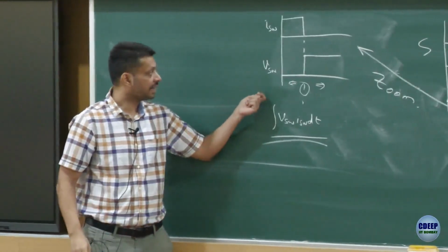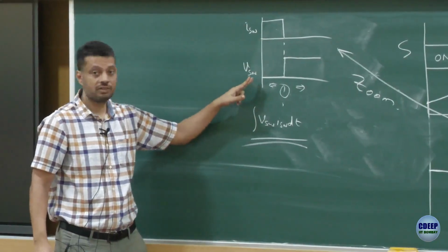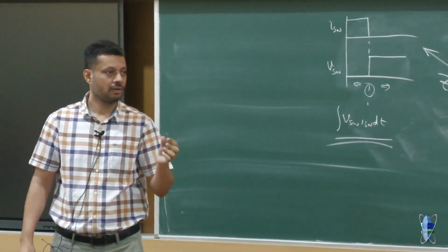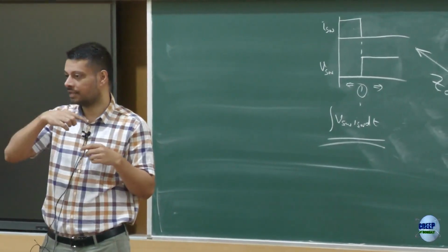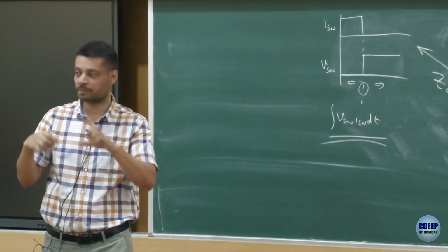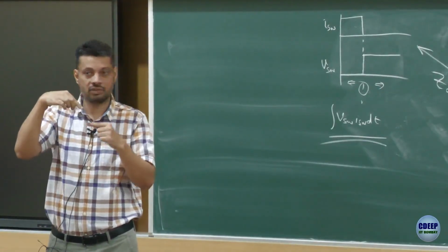If you see the left side, there is a current which is flowing and the voltage is 0, but it is not exactly 0 because the switch will have some resistive drop, because the current will flow through its channel, it will flow through the depletion region and the substrate and so on, and it will flow through the small wires which are connecting the switch chip inside.